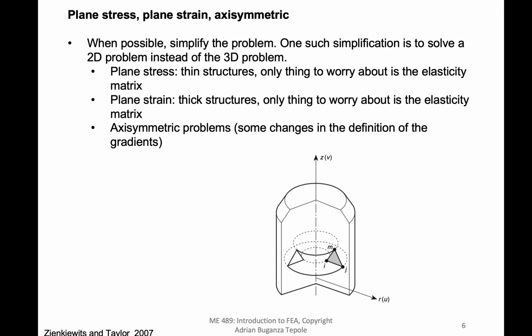In some cases, you need really fine meshes depending on the problem and the geometry, and that increases your computational cost exponentially in 3 dimensions compared to 2 dimensions. Therefore, you have to be thinking about that and avoid the 3D problem, especially at the beginning.